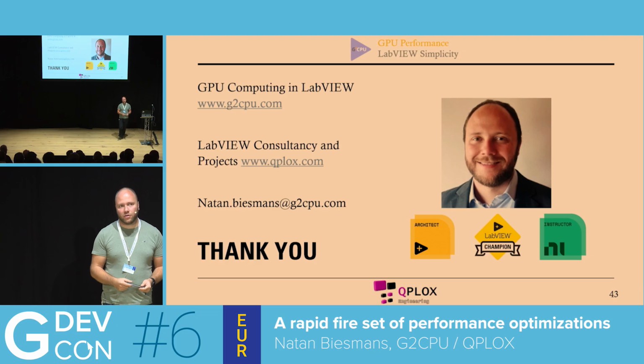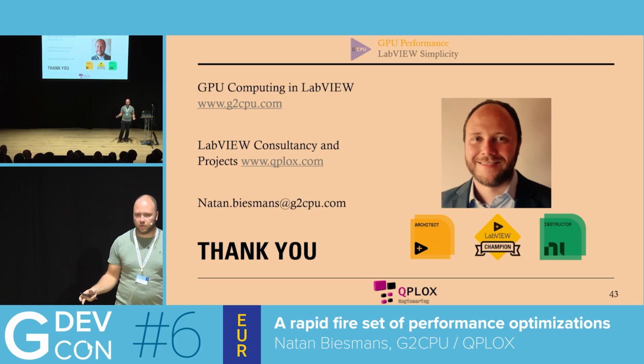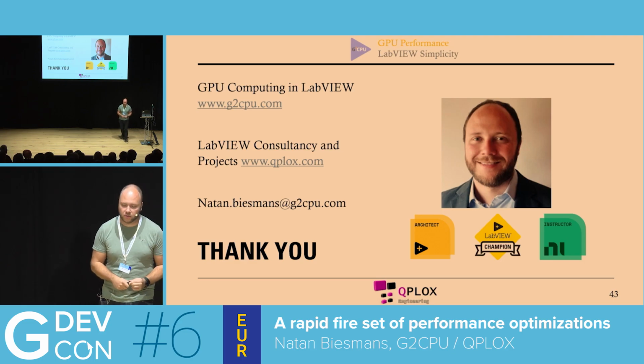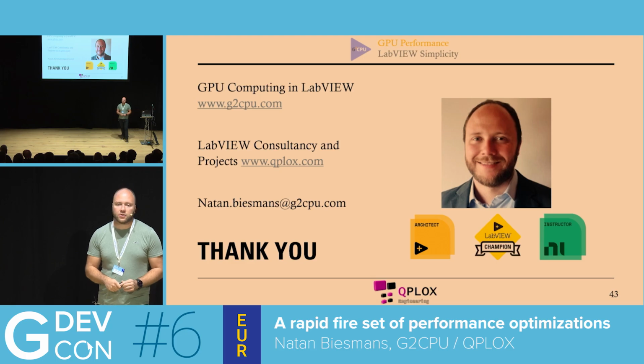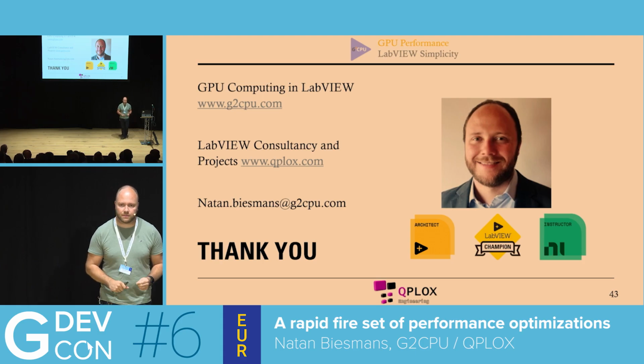But yeah, that's the only one that I've truly encountered. Maybe another thing that I did encounter was with the chunk sizes that you're writing. First of all, my recommendation is make sure it's a power of 2, that's most optimally using the hardware. But I did notice if you make a little mistake in that, suddenly it's not readable with standard TDMS read unless you use the same chunk sizes with which you've written it. So you have to keep that in mind.